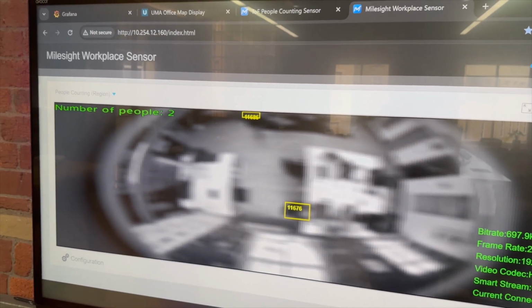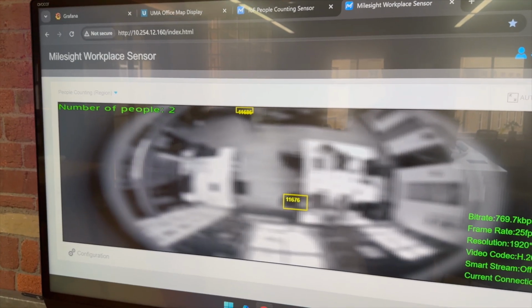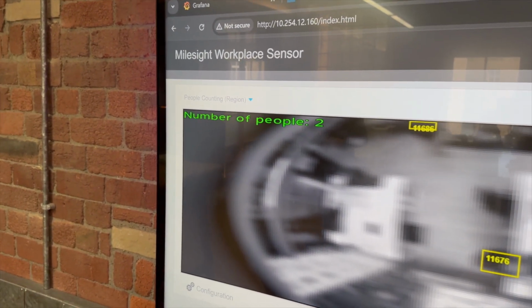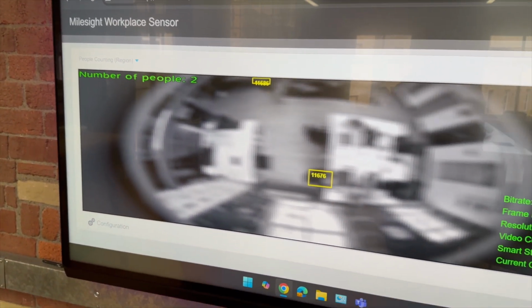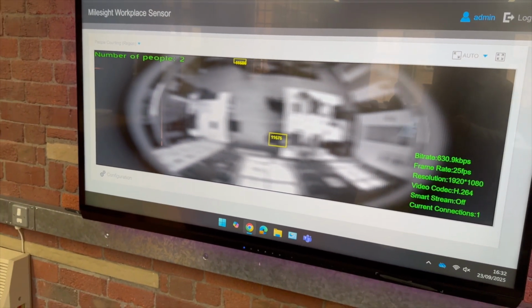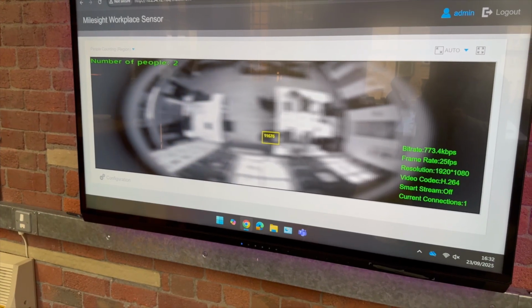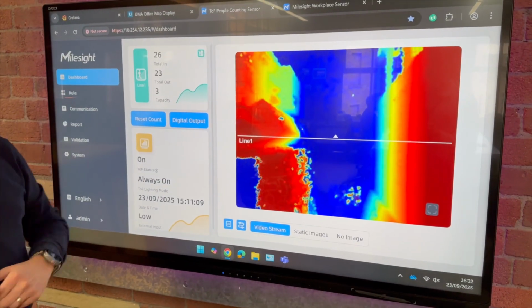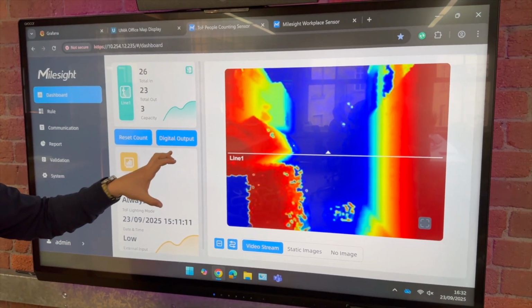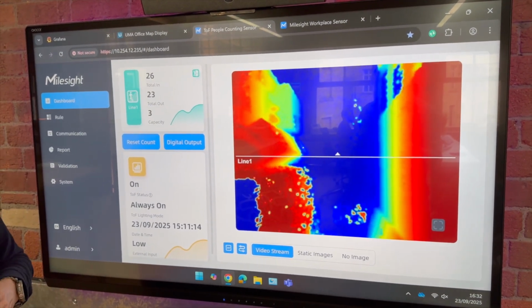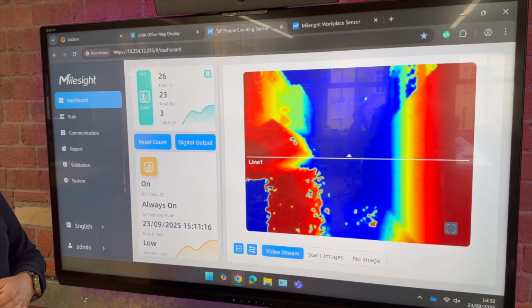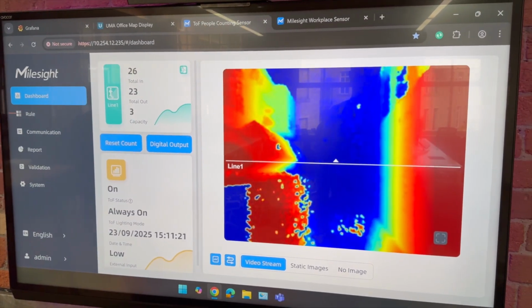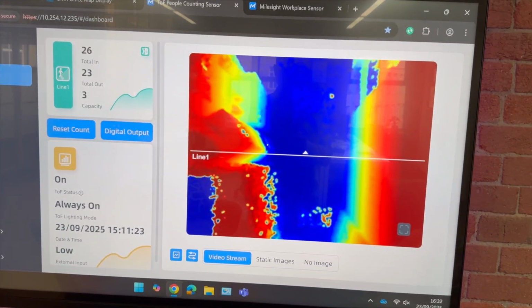And it also triggers and provides us the ability to turn the lights on and off based on occupancy. So if we then, and I mentioned this before about the other view, look at the time of flight people counting sensor, and I was to swing over here, this is what you see at the entrance and exit. So I'm going to walk out of there while you keep looking at this, and you can see what that does as I walk out of the building, and all of the infrared type technology that it has built into it.